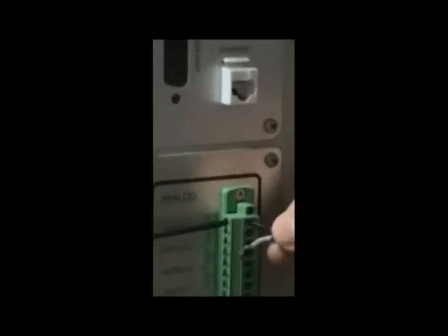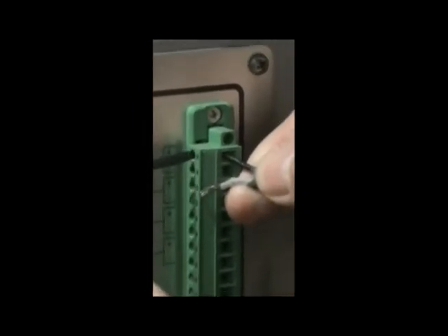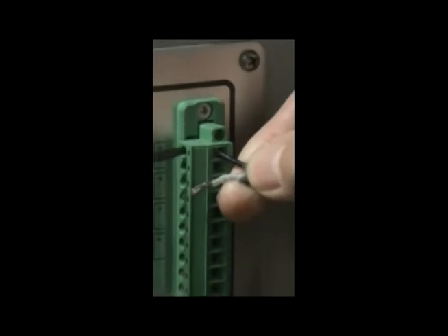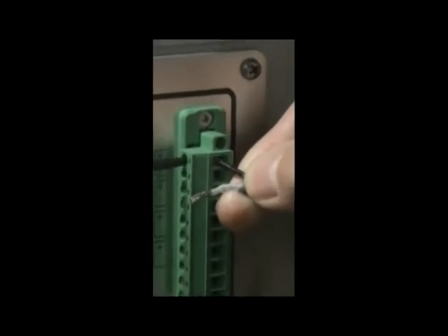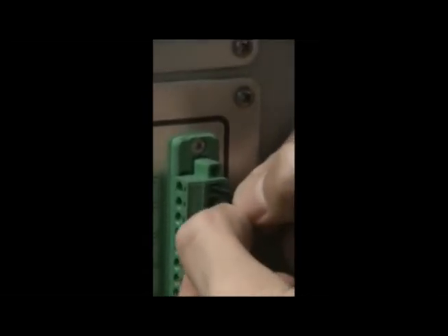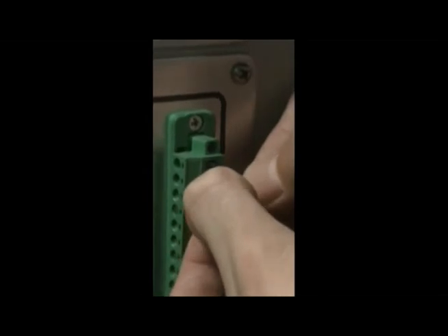The EZT570i can have up to 5 analog inputs, which are used for remote setpoint inputs. Remote setpoints are a remote linear analog current or voltage setpoint sent from an external device. The remote setpoints can be obtained from 0 to 10 volt DC inputs or 4 to 20 milliamp current inputs. The remote setpoints are enabled through events and can be selected manually or used within a profile.